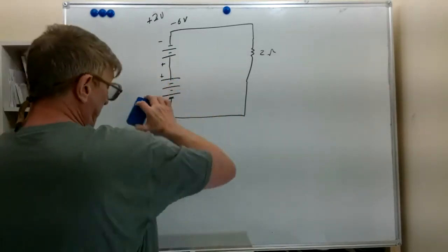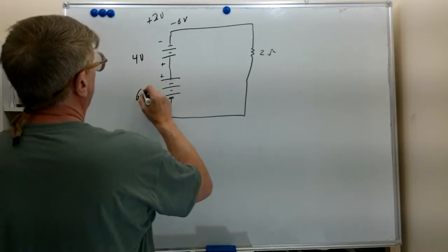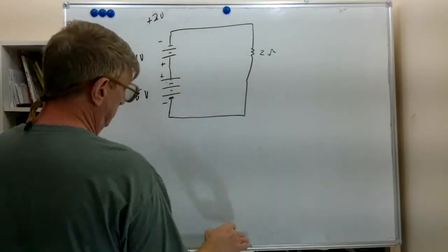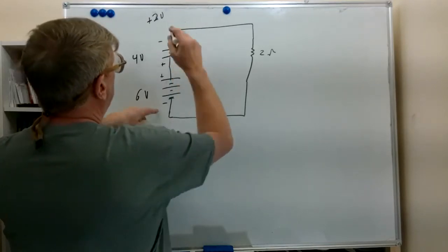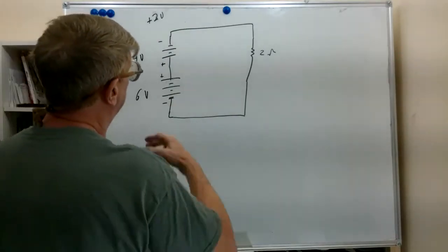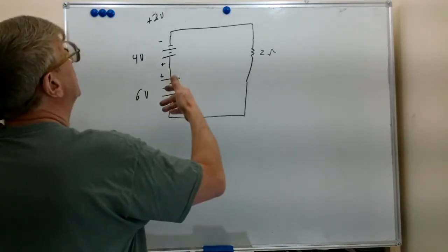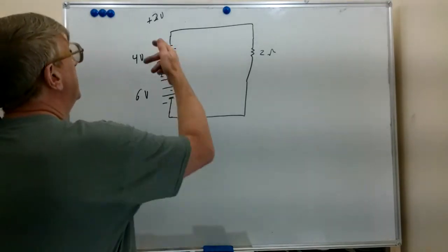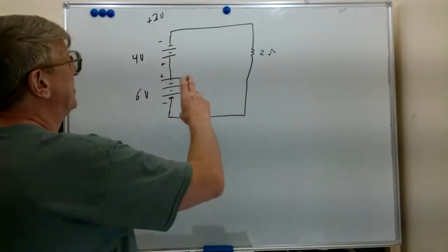But I'm going to go back to my original circuit here. We had 4 volts here, 6 volts here. Plus 6, down 4 to 2. I think I wrote that wrong. Went to negative 2, not to positive 2. When we had them reversed, it went to negative 2. But these are series opposing, so the voltages don't add up directly like before. It's a little less than the largest one by however much the smallest one is, and the polarity matches the largest one.